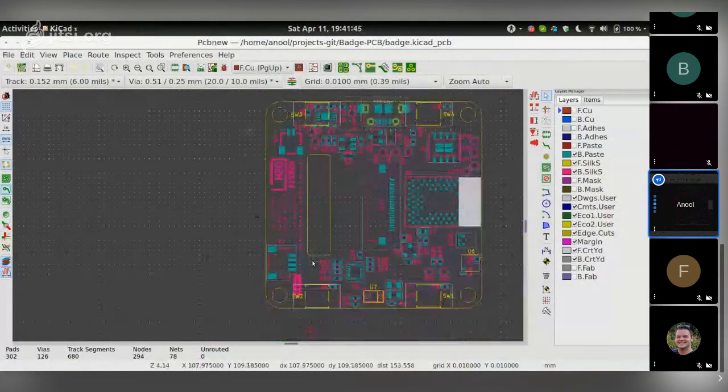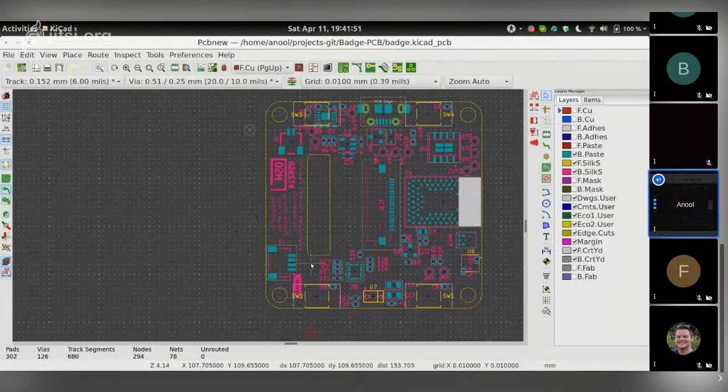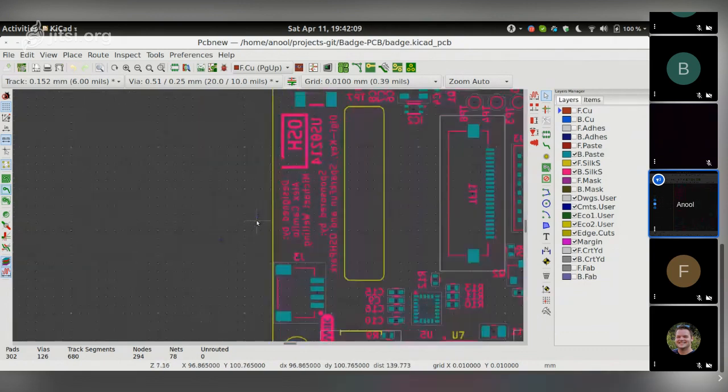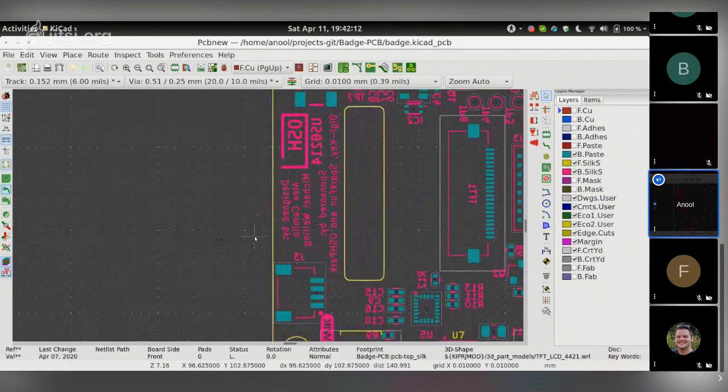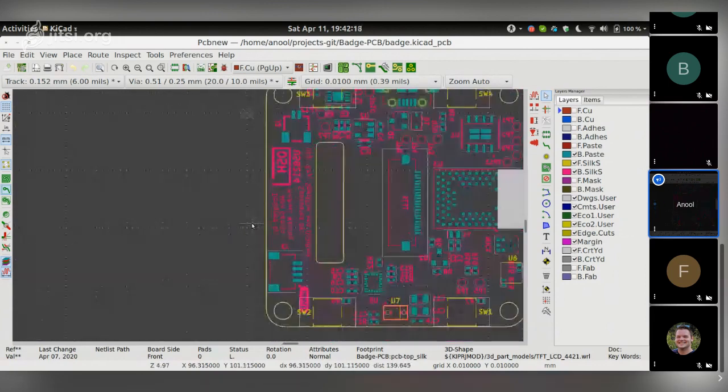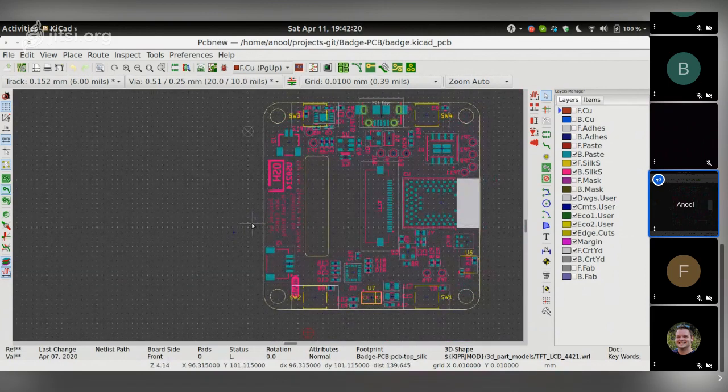So the flip side of doing the outline in, let's say, Inkscape or whatever was used, and then pushing it here as an outline, was that the DXF caused arcs to become segments. That was one. The second thing was to convert the whole outline into a footprint, with an origin at a point like, let's see, if I select this edge, you can see the outline is somewhere over here where my mouse is hovering. It's outside of the board. So these two things were not really the way you would like to do things in KiCad.